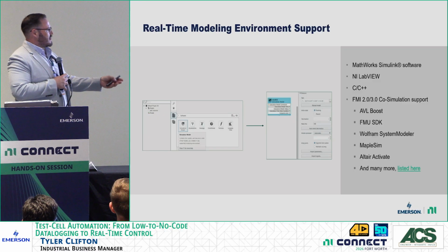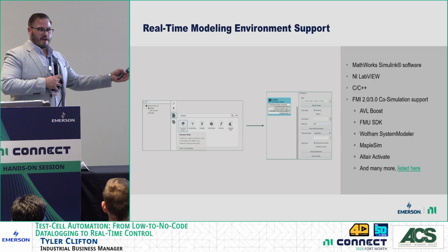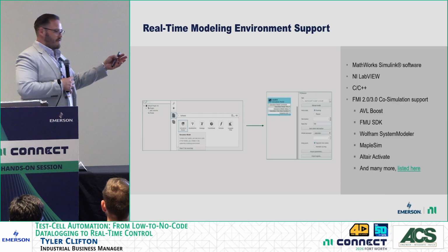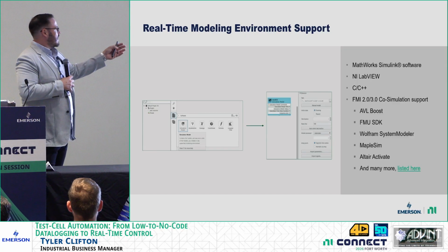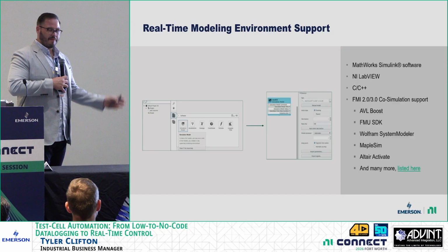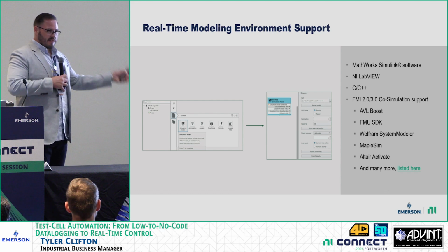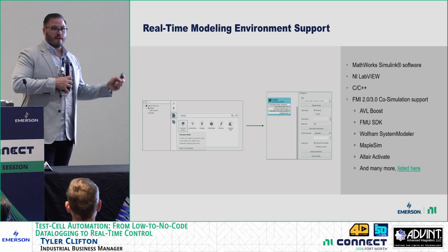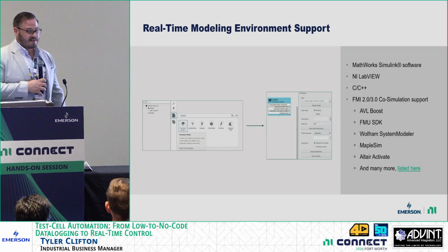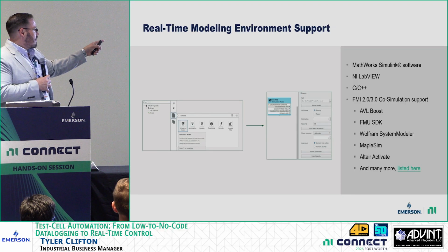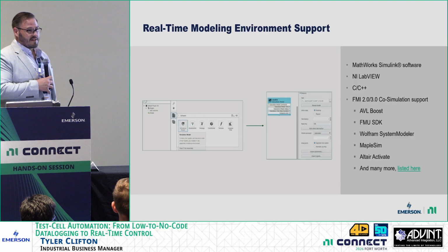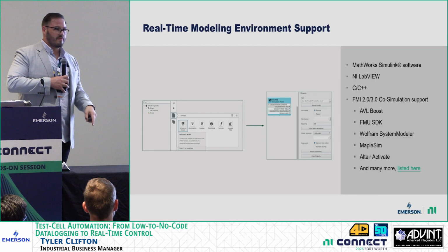And I kind of already mentioned some of this, but you can use LabVIEW to create FMUs through a LabVIEW project. And then you can also use MathWorks Simulink software to create models there. But really, any modeling software that creates FMUs, you can use. And it's as simple as selecting the software tab in VeriStand, selecting simulation model, and then pointing to the FMU.